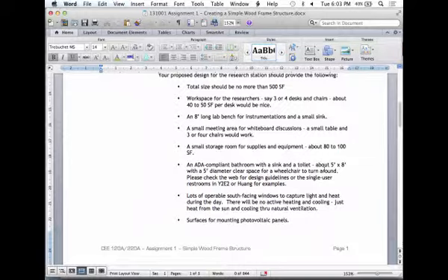In terms of your sustainability features, think about how you're using the windows. Are there windows to the south that capture some nice heat during the day that will radiate off the floor and keep the place warm? We don't want any active heating, ventilating or air conditioning in this. It's pretty much just passive. So think about south-facing windows, and maybe north-facing windows that get some nice daylight in throughout without ever getting direct sunlight. They're probably operable, so you can open them up on those hot summer days when it's going to get stifling in this place.